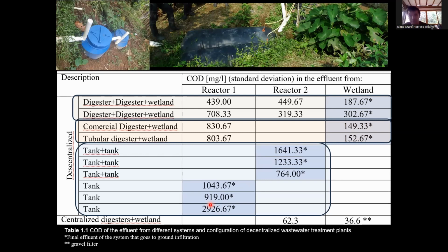Yes, we are doing infiltration now. We are putting all the effluents in the soil. But the regulation here in Ecuador does not consider the possibility to infiltrate it into the soil. So if the ministry wants to come here and measure, they will measure the effluent from the last tank or from the wetland, and they will find pathogens. So this is a legal problem. We are talking with the ministry and with the regulations here, but that is the only point.